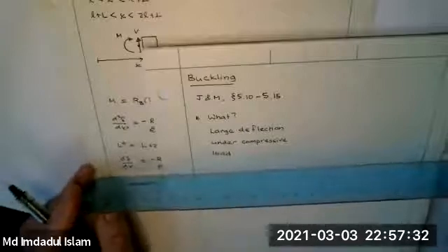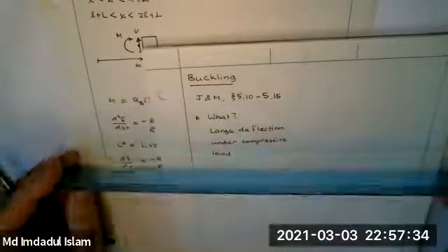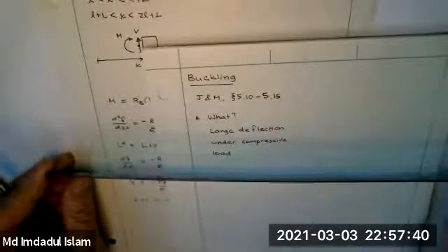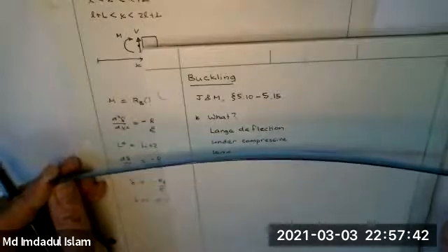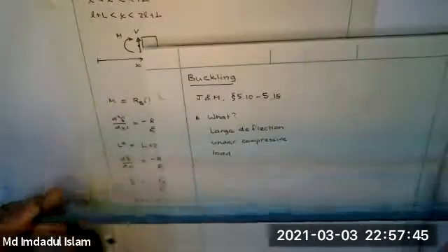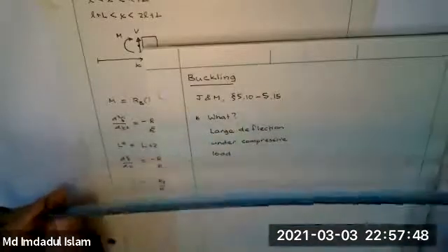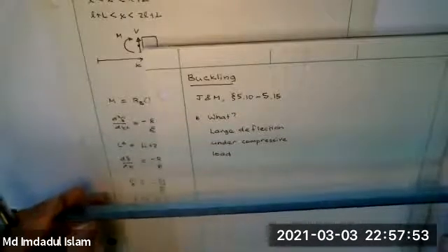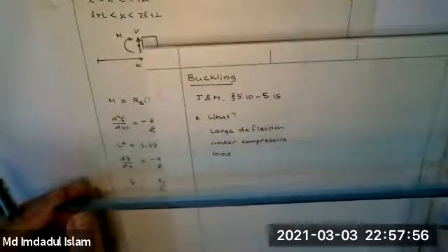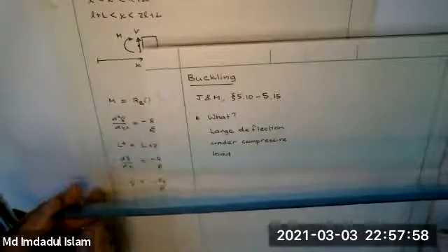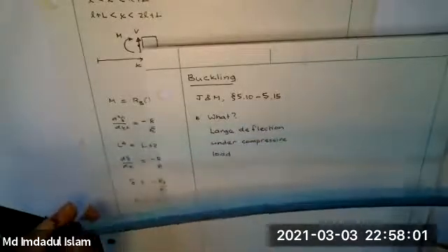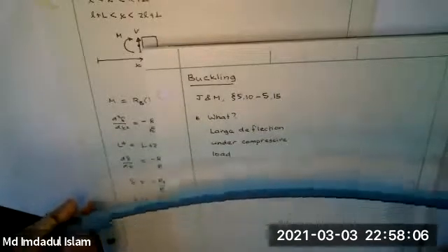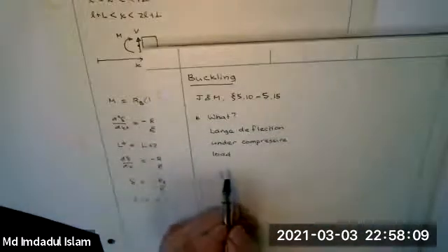Okay. So here, hopefully you can see this. Okay, now I've got it lined up so you can see it straight. There's a little bit of an angle here. I'm going to push on this ruler, and eventually you see you get large deflection. What does large deflection mean? It means the deflection is several times the thickness. You know, in that step shaft problem I did, the deflections were 10% or less of the thickness, maybe 1%. Okay, but here the deflection is a multiple of the thickness. That's what's large.